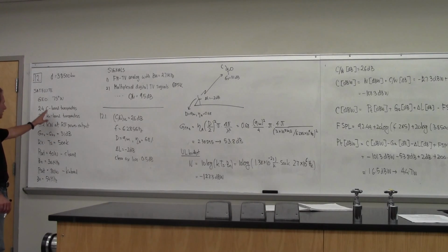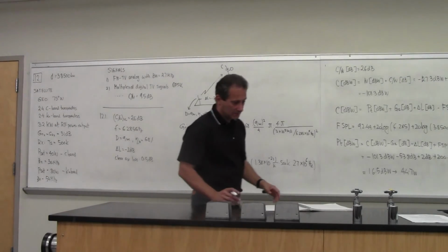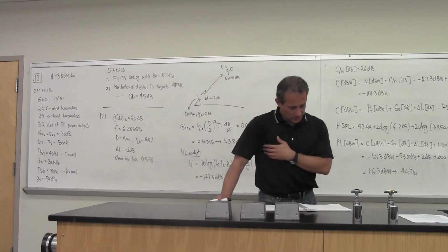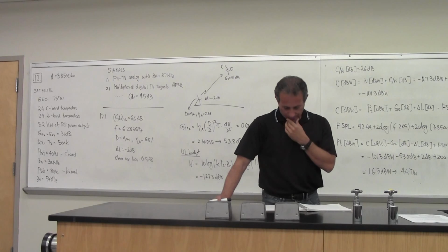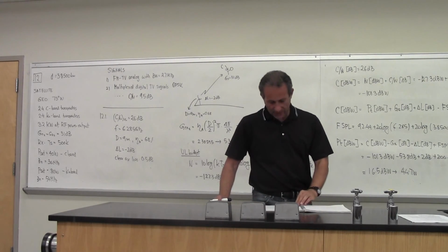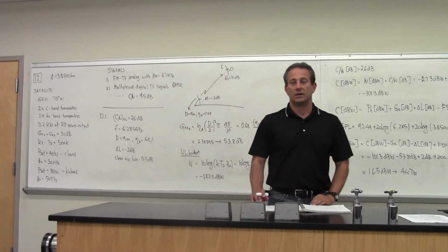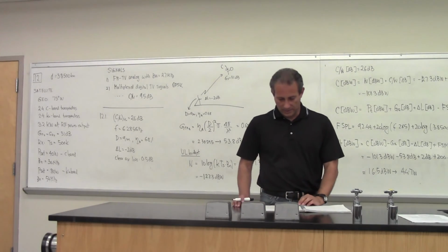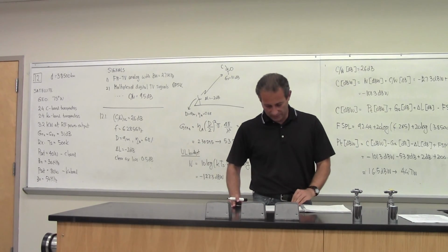Just this whole satellite is 36. So then what do we use that 36 megahertz for? I guess whatever it said in the problem, be careful. If I ask you to do that in a test, I will always say which one is the noise bandwidth. You use the noise bandwidth of the signal. That's the one that is specified, and it's never the entire bandwidth of the transponder because you have to have the guard bands.